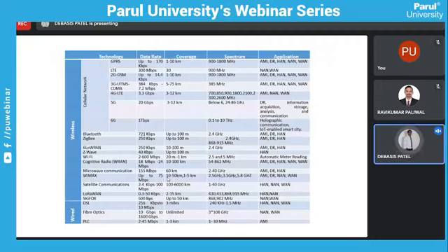Now next is the communications technology. In communication technology, this is in detail, wireless and wired. So cellular network, Bluetooth, Zigbee, low power using Z-Wave, Wi-Fi, cognitive radio, microwave communication, WiMAX, satellite communications. All these are wireless, and wired communication includes fiber optics, power line communications, DSL. So these technologies have data rates, coverage area, spectrum, that is bandwidth, and applications, right?